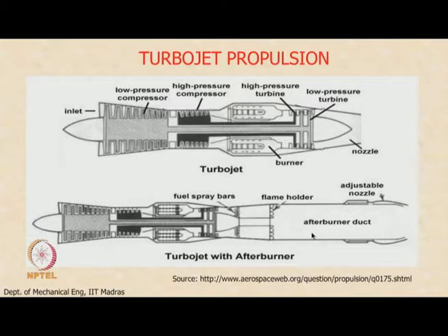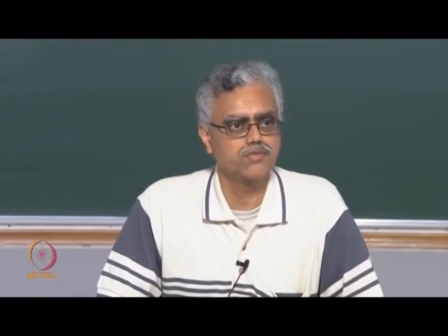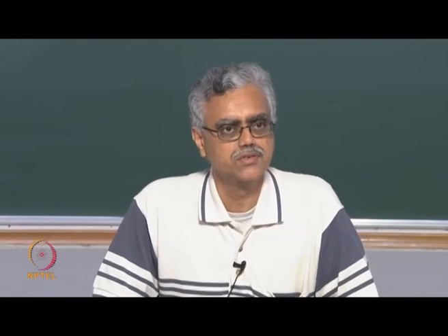But this can be utilized only for short durations of time, to punch through the sound barrier to attain supersonic flight speeds, because this can be extremely inefficient from a fuel consumption standpoint. But for military aircraft, especially for bursts of acceleration, this is an extremely good technology to use. For taking off from an aircraft carrier and for sudden bursts of acceleration during combat maneuvers and so on, this is a very good technology to use. But for sustained cruise, we need to employ a different technology.